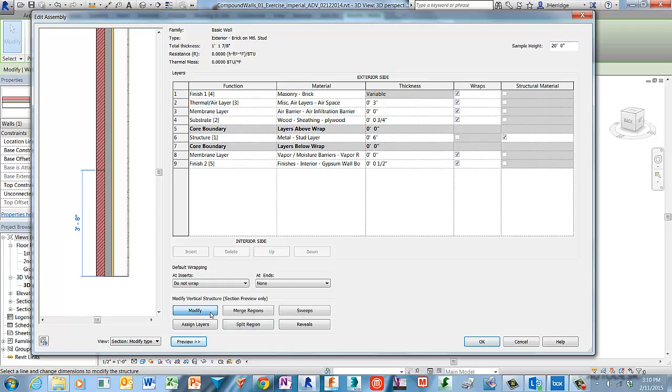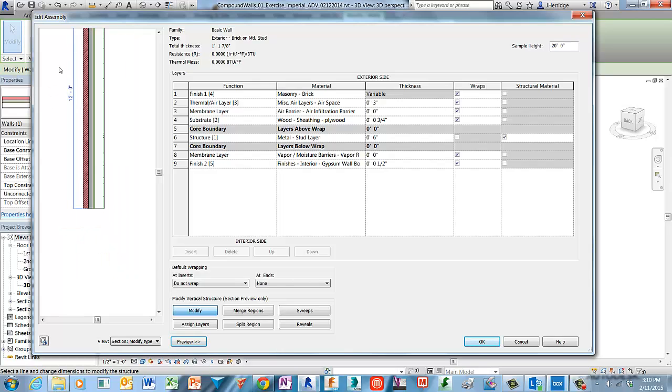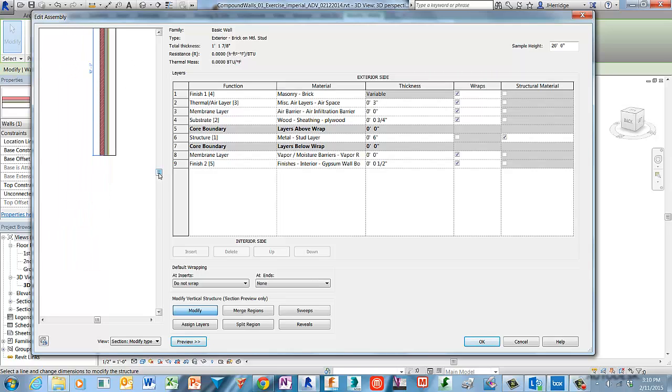After you place the split line, go ahead and click the Modify tool and click on the split line. And let's give it the value of 12 feet. So enter 12 and then hit the enter key to accept. Split line appears above the preview window or out of view, so let's scroll and pan the preview window accordingly to see where that split line is with more detail.